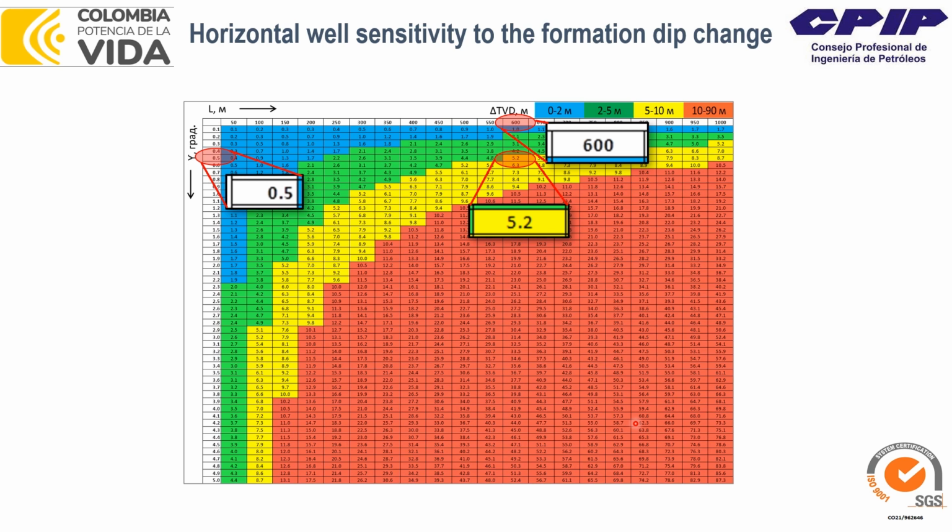So every change in the depth is critical, and you need to have the geosteering technologies and services applied in this well. So no geometrical drilling. It would be catastrophic to drill this well geometrically with such a long horizontal section.